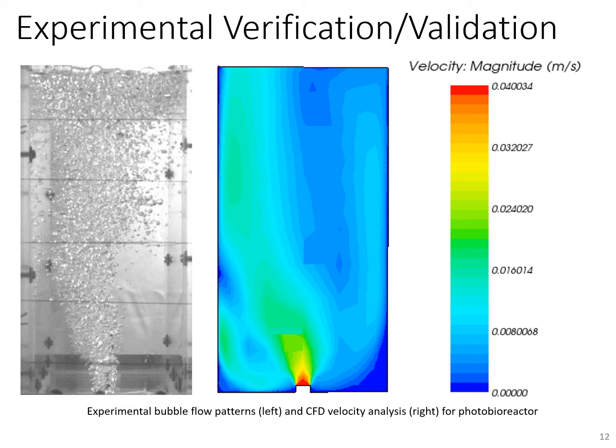Both flows tend to attach to the left wall before expanding out throughout the entire column, with some recirculating through the column before releasing toward the open top of the photobioreactor. This is likely caused by the forces of the bubble drag as they flow through the fluid and interact with each other, particularly as the bubbles begin to recirculate and get caught back up in the bubble jet stream for an extra pass.